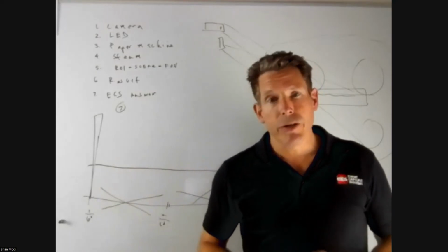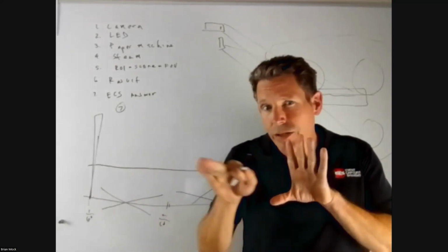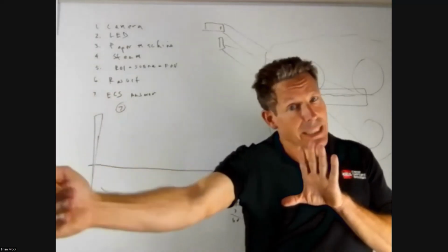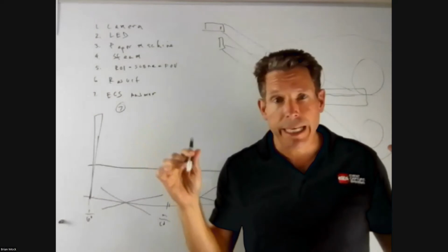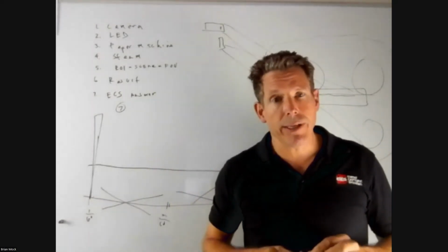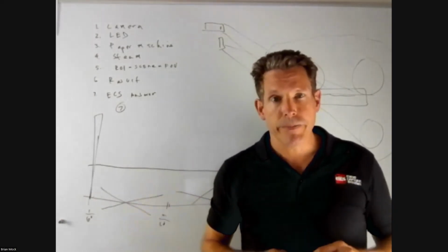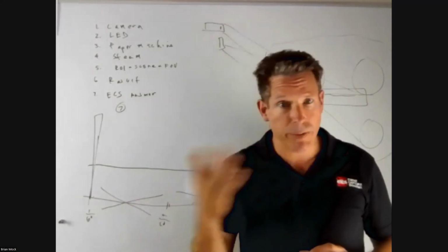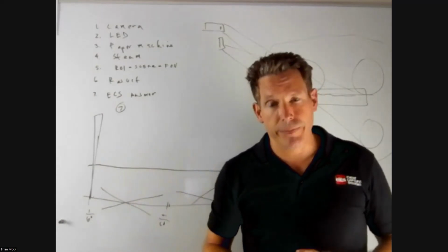Number two, you have no depth of field. That means that with cameras on the outside of the machine, there's no way to get focus on the middle or even maybe the back edge versus what's on the front edge, because your iris is wide open and you cannot get focus. If you can't get focus on the item, what do you think that dot or that defect or that blemish is going to look like? Well, you're not going to see it. Operators aren't going to see it. Your vision system isn't going to see it, whether it's a web inspection system or a proactive sheet condition alarm. It's like it was never there.